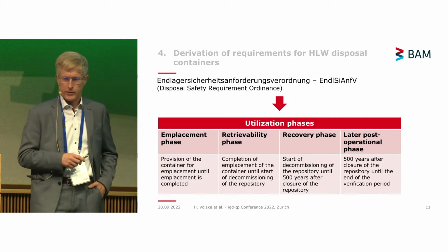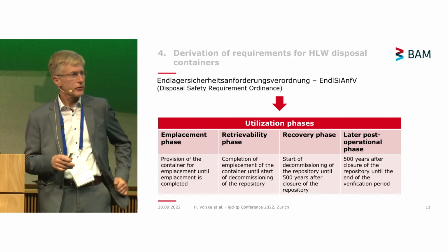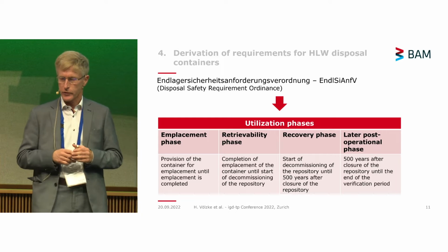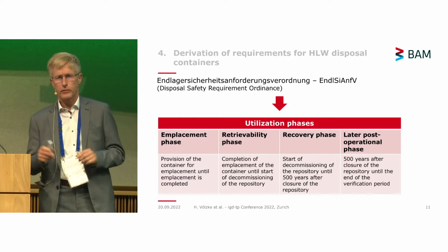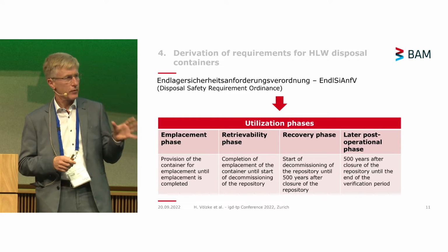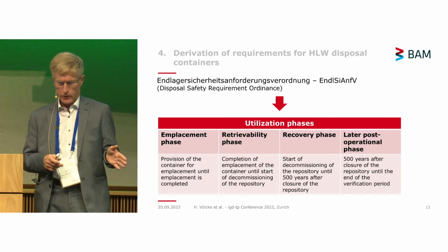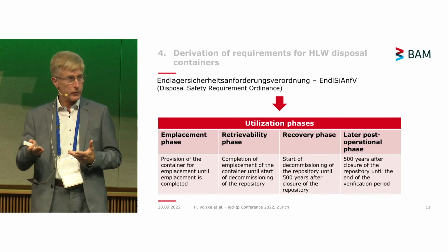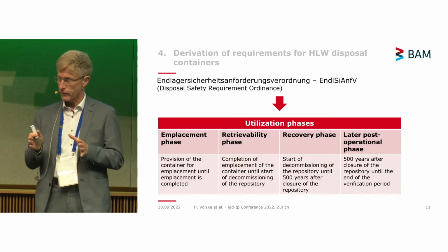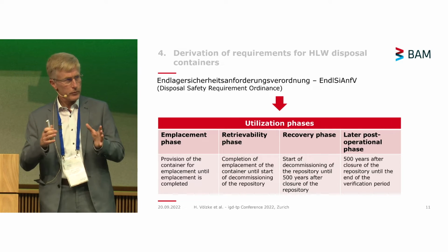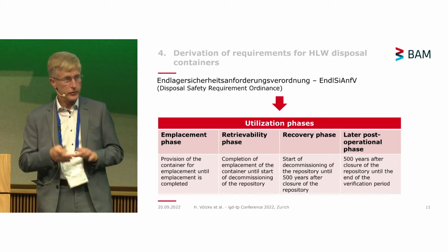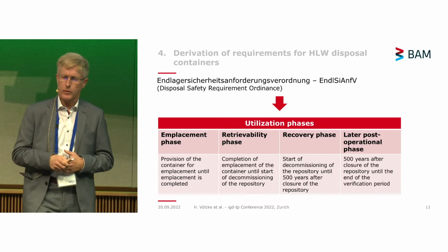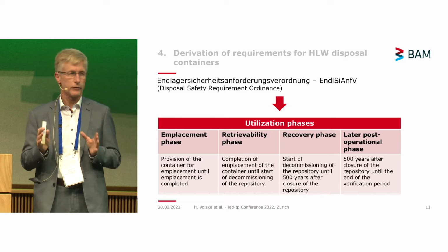And especially this Disposal Safety Requirement Ordinance in Germany, which is addressing this, differs between different utilization phases of the repository, which means we have the emplacement phase at the beginning. Then after completion of the emplacement of the containers until the start of the decommissioning, we have the retrievability phase, which means we need to be able to retrieve all the packages if necessary for some reason. And this is followed by the 500-year recovery phase.